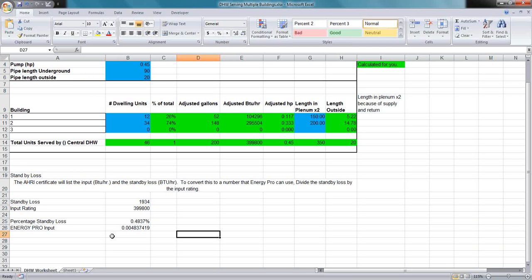Next question is, how do you simulate primary and secondary pumps? A primary pump may be on constant volume, and a secondary pump may be a larger pump that is a variable frequency drive pump. How do you simulate this type of system? I've started to see this more frequently in newer or retrofit boiler rooms where you've got two pumps on two skids sitting next to each other on the ground.